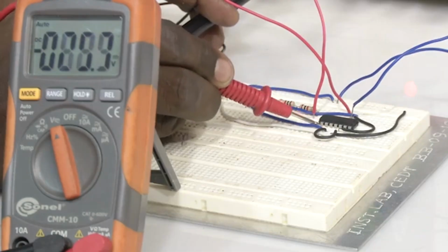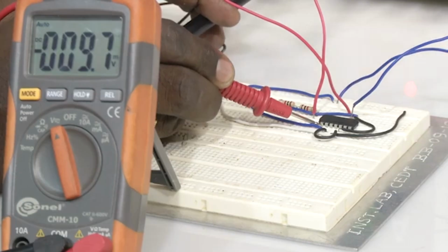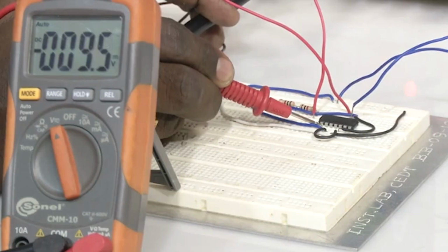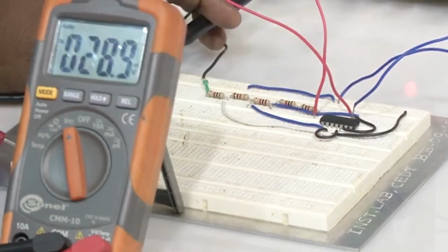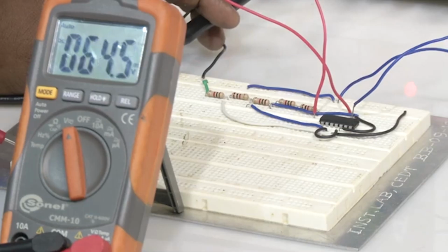Now, when I see the output voltage, the last pin, it shows 9.6 millivolt, which means that it is 0. So, that is what we have seen, right. If the input voltage is greater than 1 volt, C1 will be 1, whereas C2 and C3 will be 0. 0, 0, 1 is the output from all the 3 comparators. When we pass through an encoder, it gives you output as 0, 1, right.